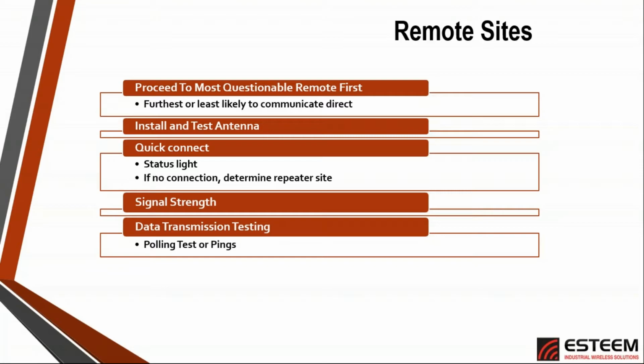If you have enough signal for reliable communication, we then basically want to put data across this network, because the data is going to tell us how well those two radios are able to process information between each other. Now, for the type of testing that you put across there, one of the most efficient means of doing this, especially since most of our radios have Ethernet interfaces in them, the easiest way to do this is what's called a ping test.